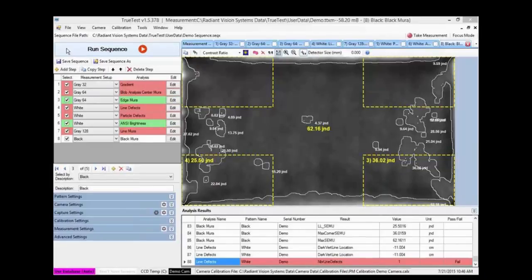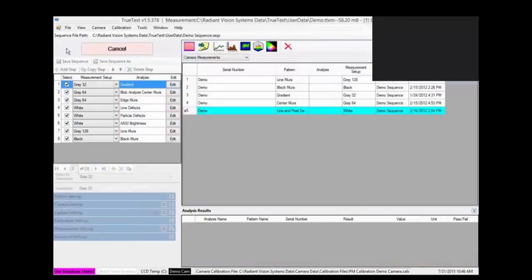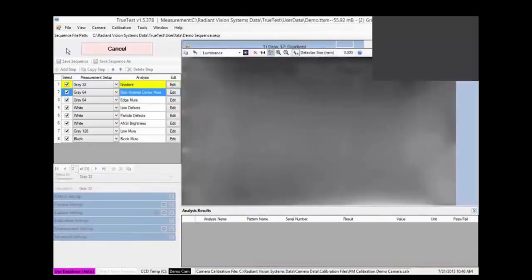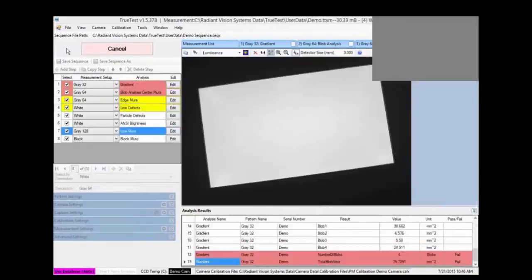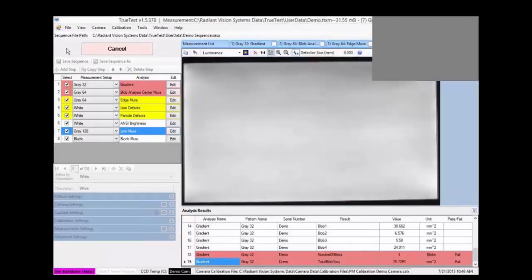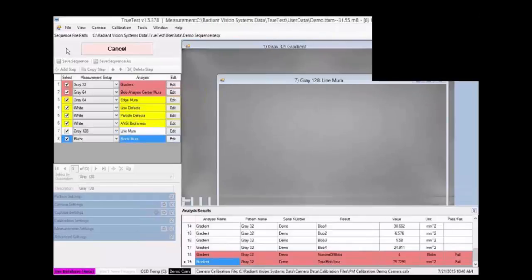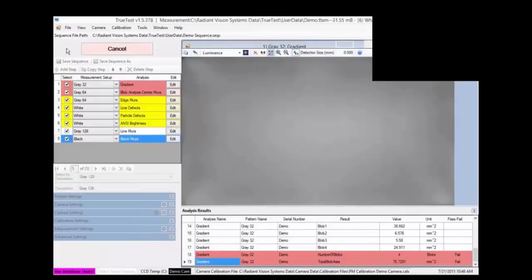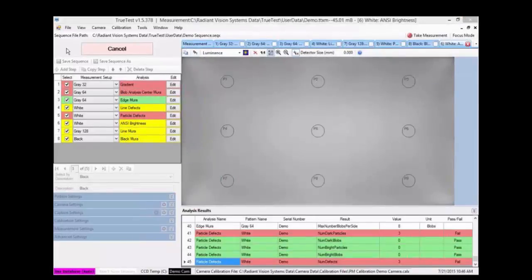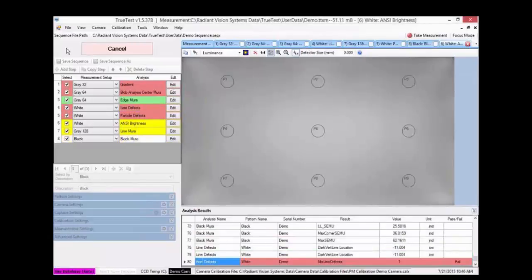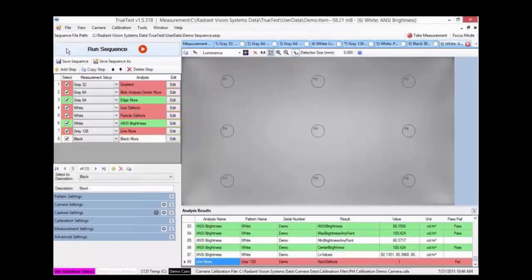So let's go back to the fast image again. For each step, this is a real-time video of it in action. Each step in the sequence is doing the pre-processing. We're taking our measurement, finding the corners, cropping it out, removing any moire, and finding the reference image, and then comparing the original to that reference to produce this contrast image. And doing it all multi-threaded and as fast as possible, because in production, speed is king.